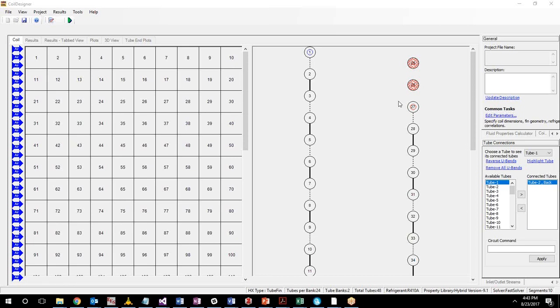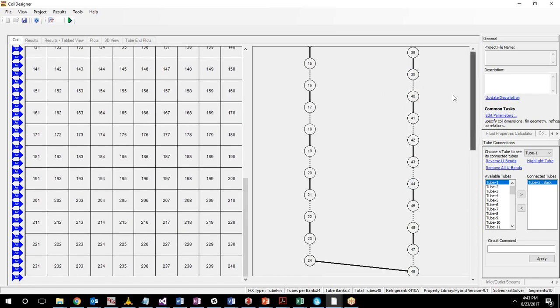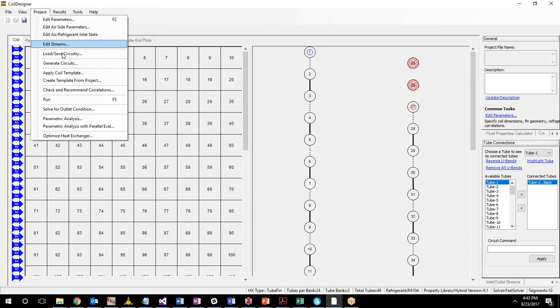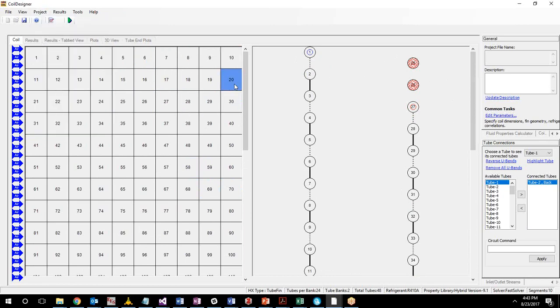There's another question about leaving out a notch for some interference that's blocking flow, and we can account for that by specifying the air velocity profile that comes into the heat exchanger. The assumption here is that everything is uniform, which is rarely the case. But if we want to specify that some particular section of the coil doesn't receive airflow in the same way that the rest of the coil does, we can reduce or eliminate the velocity of the air that enters a particular segment. So if you think of this as a grid, we can specify any part of this coil face area and reduce the velocity there to represent something more realistic as far as what is the real velocity distribution when you have all the blockages and non-uniformities that come from the enclosure where this coil is actually installed.